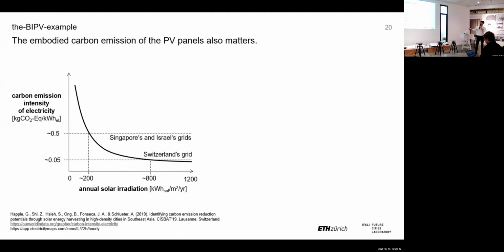So this curve represents common PV panel types and the carbon intensity behind them. How do we use this chart to determine where on the building facade is eligible for PV panels, in order to have the PV electricity yield coming out of the PV panels have lower carbon intensity compared to those coming from the city electricity grid?